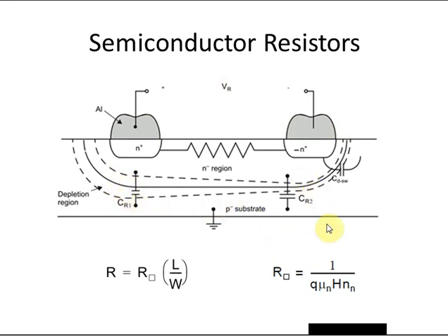So all of these things pose some problems for analog design. The fact that the capacitance is changing as a function of voltage implies that there's a nonlinearity there, and that can lead to distortion of analog waveforms. Also, the fact that the parasitic capacitances are not balanced may be a problem. If we're trying to use this across a differential signal path, then both sides won't be seeing the same capacitance. So, a couple of challenges there trying to use these types of resistors for critical analog applications. So it's usually avoided for those types of applications.